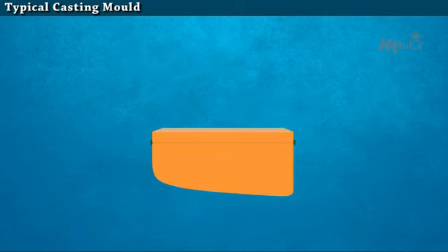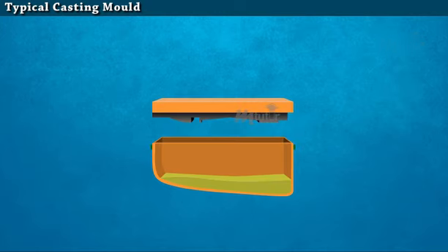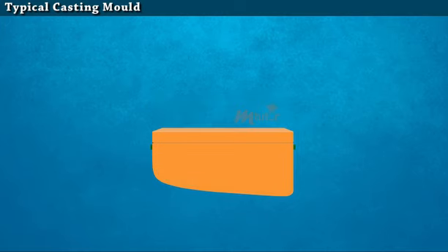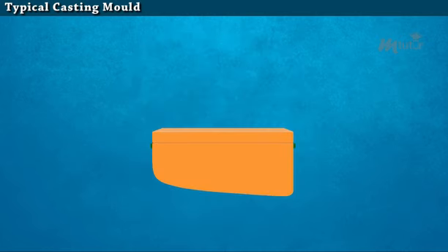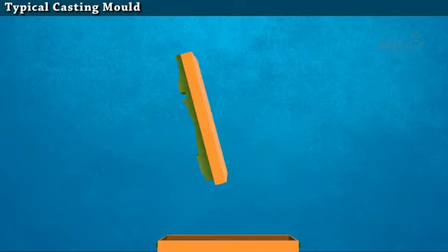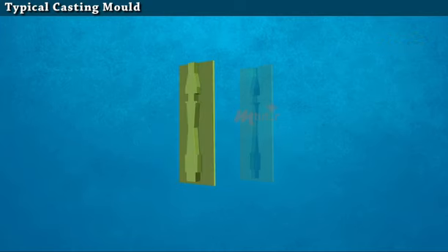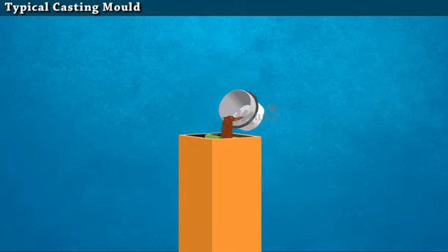Moving on to the shell mold casting process. Sand free from clay is mixed with resin and put into a dump box. Then, the metal pattern is covered as a lid. The box is turned over and kept for 15 to 30 seconds. The sand gets coated on the pattern. After hardening, the mold is removed from the pattern with the help of ejector pins. These mold halves are assembled and metal is cast to obtain the desired product.